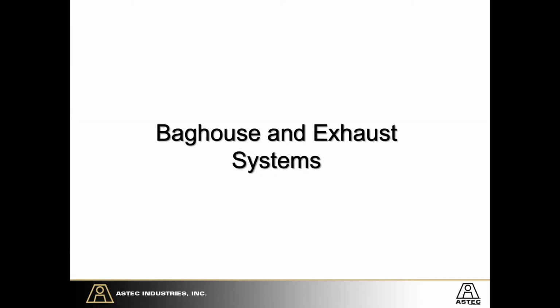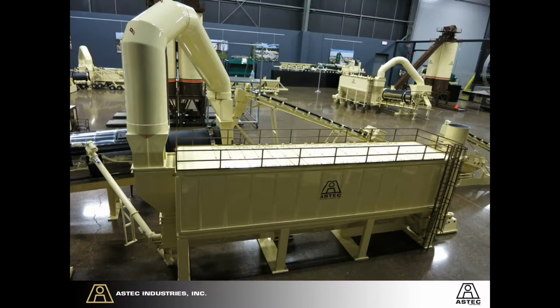When we talk about the baghouse and the exhaust systems, this is a pulse jet baghouse. You can see here's the stack that comes over. This is pulling the fine material over, the -100, -200s. This particular one has an inertial separator. Here's the baghouse body and then the exhaust fan on the end.